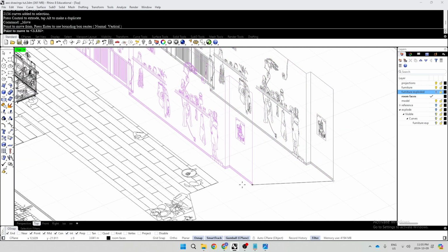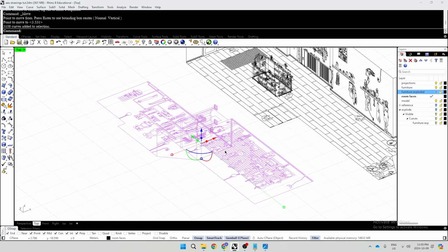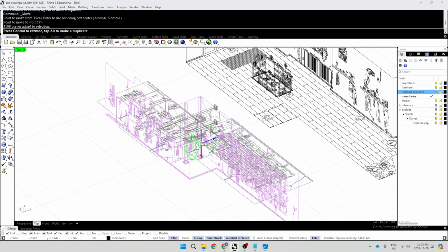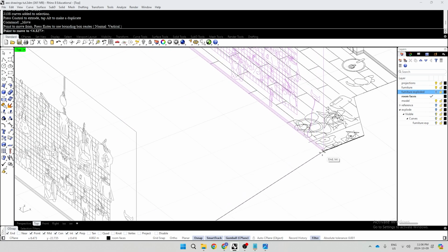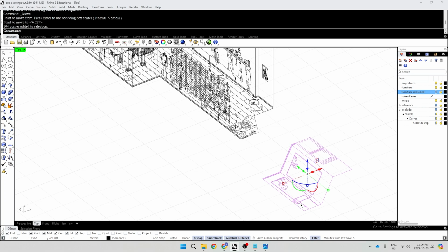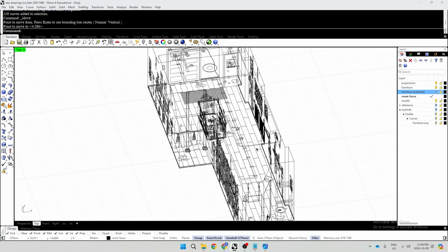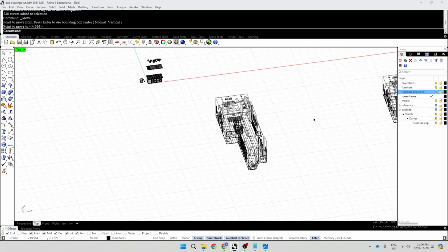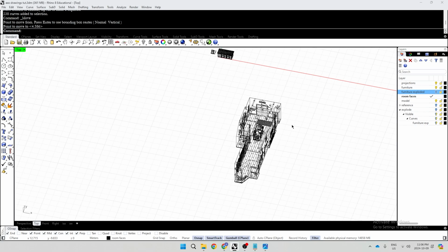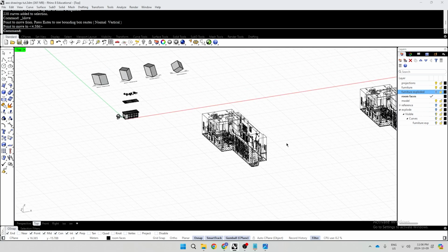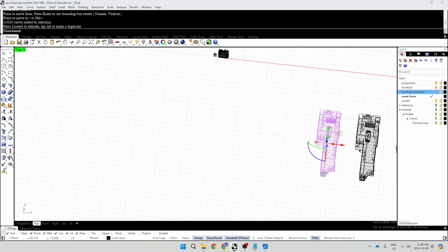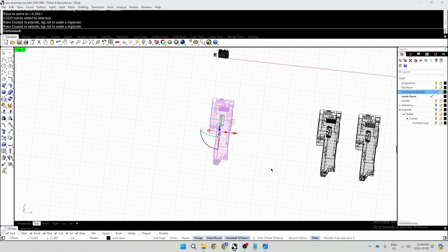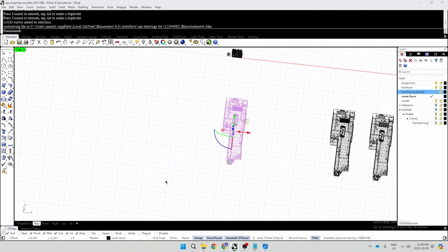This technically should line up perfectly because you are drawing elevations and plans of your room that is measured, so everything in theory should match up. After you're done with this pseudo 3D model, you can make all sorts of projection drawings with it. So first, let's do an ISO like we just did. Before you make any drawings, always make a copy because this will mess up your model. Alright, to make a copy, I'll isolate this again.